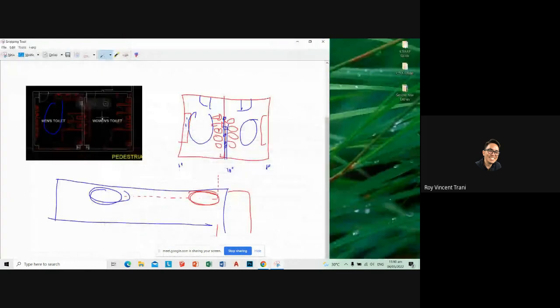Anyway, the general concept is that, for example, this is a road here. There's a road in between your entrance and your lobby area. There will be tactile pavements on the sidewalk that connect to the entrance of your building. And then from the reception area, there are tactile pavements that will guide the visually impaired to the waiting area, or to the ticketing area and maybe some withdrawal areas. And then more. It basically tells them where to go.